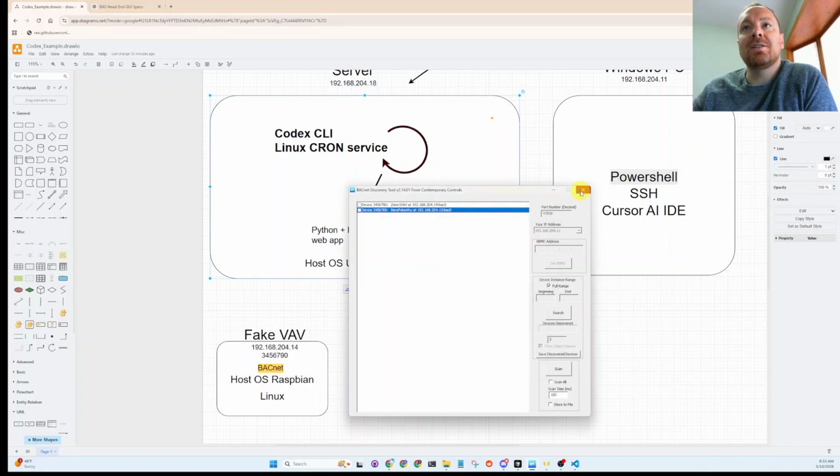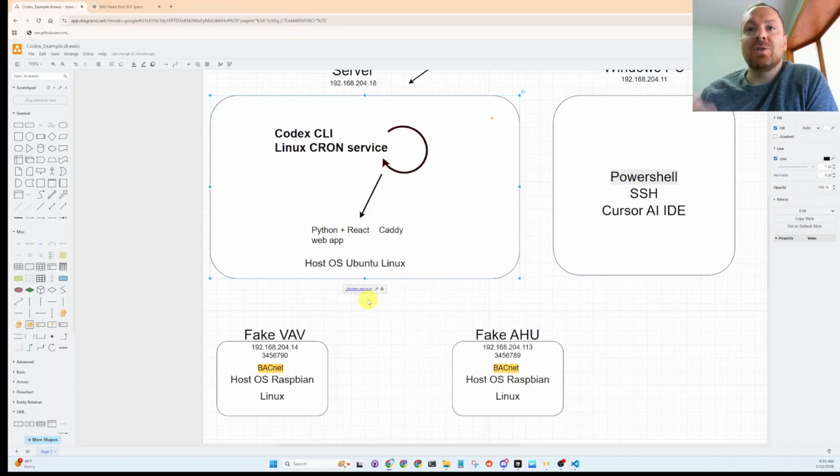And they do that because every device in the building automation system can't have its own outside air temperature sensor, mostly due to cost. It would take extra wires for the building automation contractor to run. And sometimes if this is in a mechanical room in a poor location, you might not be able to run a wire, so you just use the network to communicate that value.